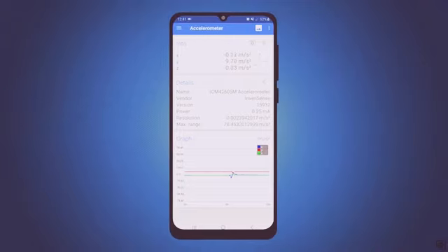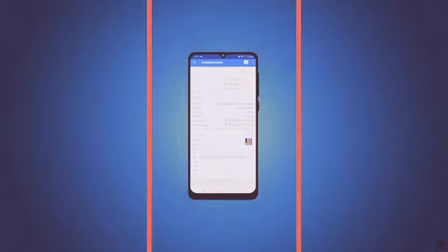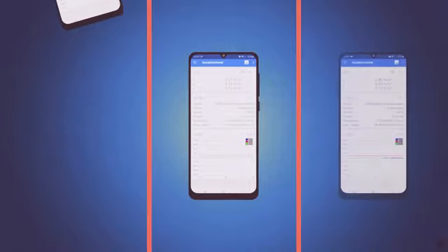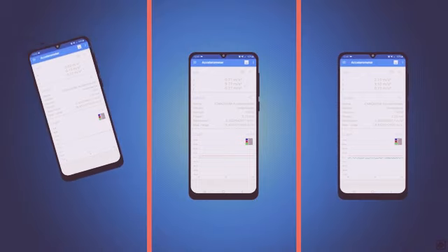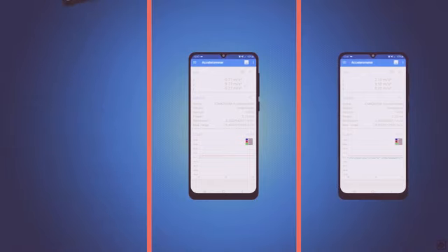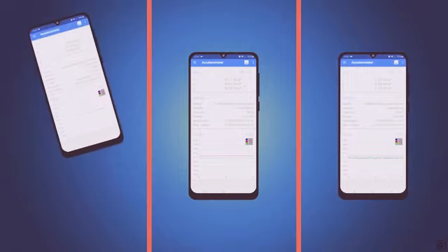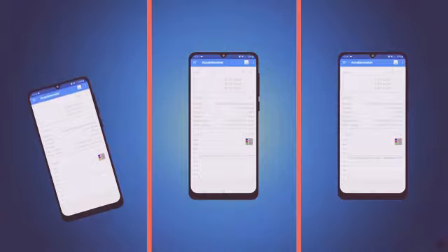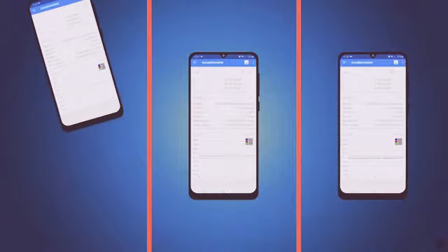So when the phone is at rest or moving at a constant speed, the accelerometer's data is not zero, it's equal to the gravitational acceleration. The accelerometer's output is only zero in free fall. In any other situation, the output of the accelerometer is the gravity vector plus the acceleration vector. So when the phone measures the acceleration in a particular direction, and it's nearby to the acceleration due to gravity, then the phone knows which way is down and thus reorients itself.